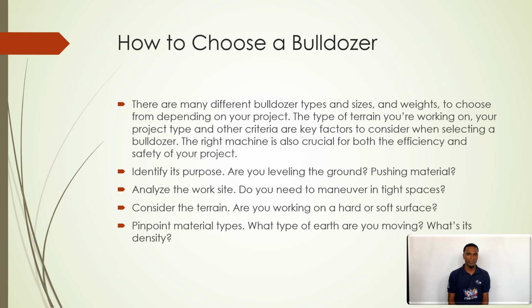Identify its purpose. Are you leveling the ground, pushing materials? Analyze the work site. Do you need to maneuver in a tight space? Consider the terrain. Are you working on a hard or soft surface? Pinpoint material types. What type of earth are you moving? What is its density?